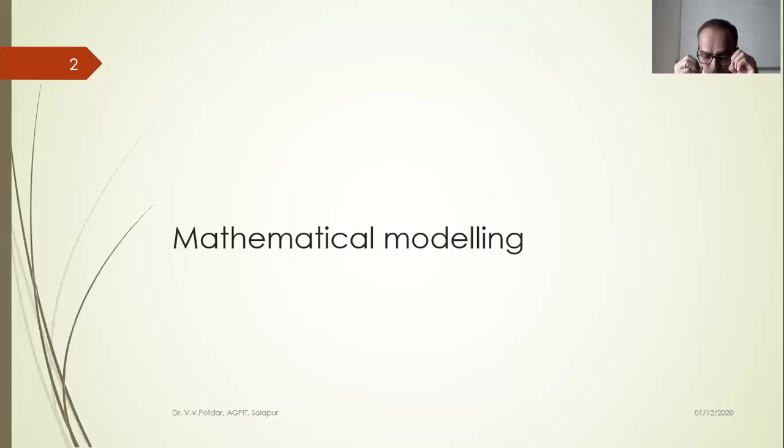If I'm talking about a carburetor, let us say, which is a known example for us. What is the functionality? What is the specific task the carburetor does? It receives air, it receives fuel. The carburetor mixes it as per the signal strength I want, whether I want a richer air fuel mixture or a leaner air fuel mixture, and it will give the outlet as appropriately mixed or chemically correct air fuel mixture to the engine inlet manifold, isn't it? That is the function of my carburetor.